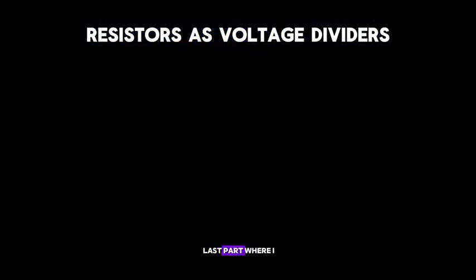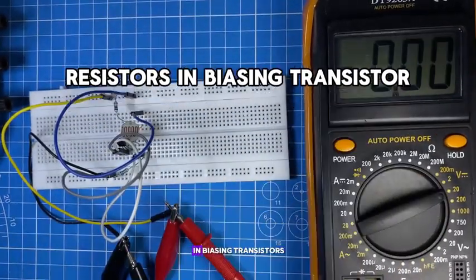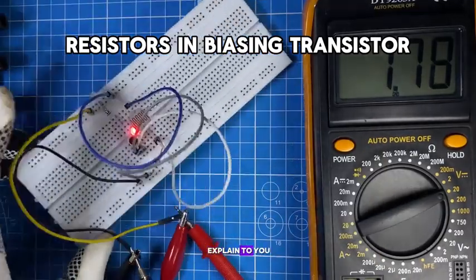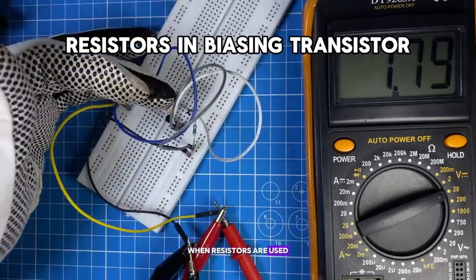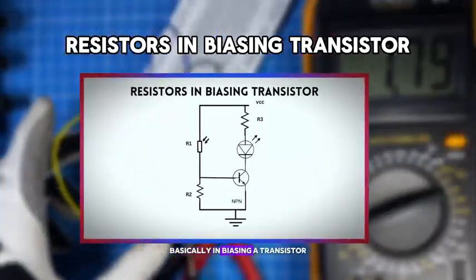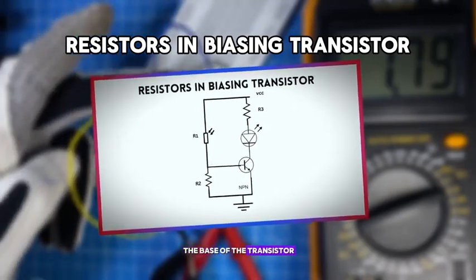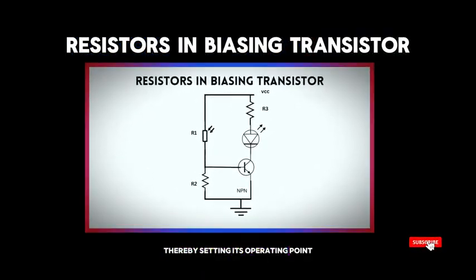So this is the last part, where I am going to explain to you step by step and practically how resistors are used in biasing transistors. But before that, I believe it is also very important for me to explain what it means when resistors are used in biasing transistors. Basically, in biasing a transistor, resistors are used to control the voltage at the base of the transistor, thereby setting its operating point and determining how much current flows through the transistor. They act as a voltage divider to provide a stable and precise bias voltage to the base, minimizing the impact of variations in the transistor's beta value and temperature changes.